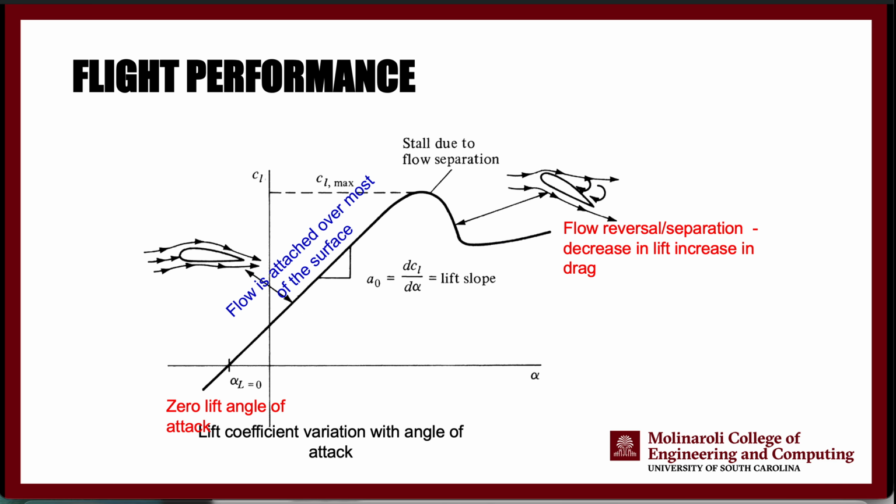And this is, again, lift coefficient versus the angle of attack, the most important performance metric of an aircraft, and this is the graph I need you to give me in addition to the other graphs, right? The idea is you have a couple of important points on this graph. One is this 0 point. This is where your lift coefficient is 0, and the angle of attack at which the lift coefficient is 0 is an important angle for us.